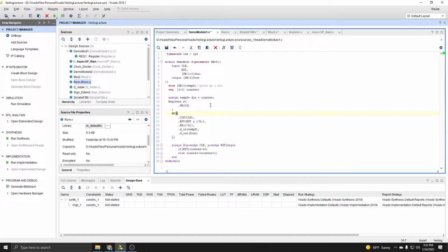The all caps version does work, but I typically just add numbers to things, or add a very unique name, because you'll often be instantiating several of that module in a top module, and this allows you to uniquely identify them. Plus, on top of that, it is required by the Verilog syntax.